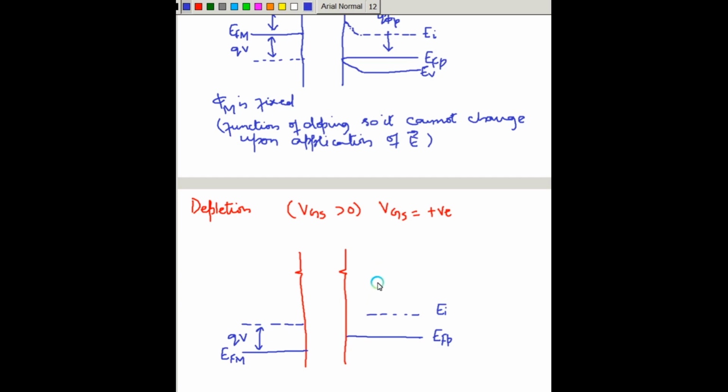For the rest of the semiconductor, we'll first draw the same diagram as it was before. EV. Now along the interface, we have to denote a material which is more of an n-type material, which will be done by moving the Fermi level closer to the conduction band or closer to the intrinsic energy level. So the intrinsic energy level will bend downwards like this. So there will be a bending of the bands which is downwards.